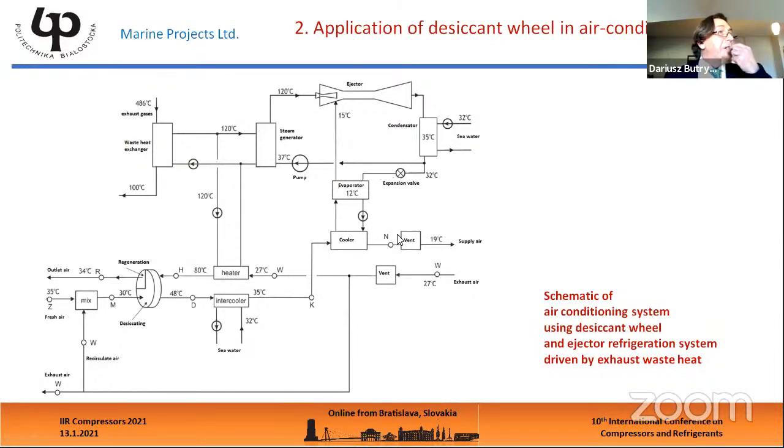And so this approach creates possibilities to apply as large as possible application of waste heat in the air conditioning units, and reduce a refrigeration capacity that is needed by air conditioning system. And also, you see, it is possible to use also very high evaporation temperatures. So first, you have eliminated as much as half of refrigeration capacity. And the second point, you can increase evaporation temperature so that your refrigeration system independently will be compression, ejection, whatever it could be, will be much more effective.